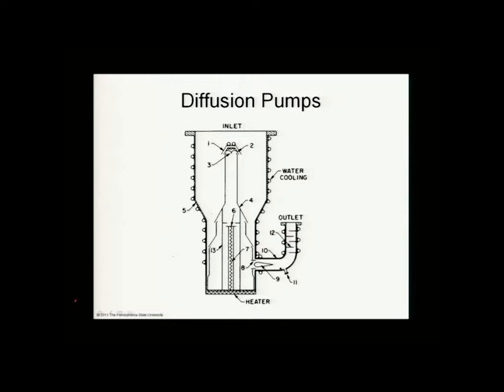Here we have in this view graph a schematic of a diffusion pump, and let's just talk about how it works. As you see in this schematic, the inlet is coming from the vacuum chamber, so the gas molecules are bouncing their way down to here, undergoing collisions, bouncing into walls. Then the oil jet is set up to capture those molecules, entrain them, give them momentum that really directs them this way.